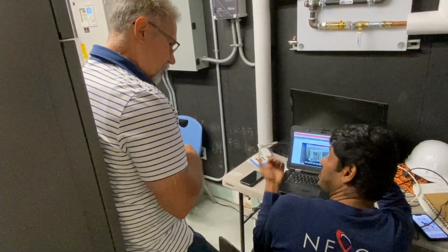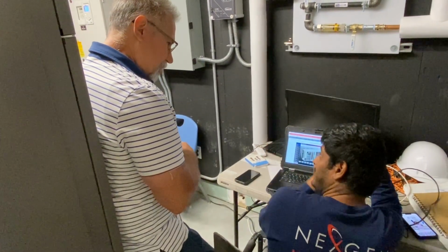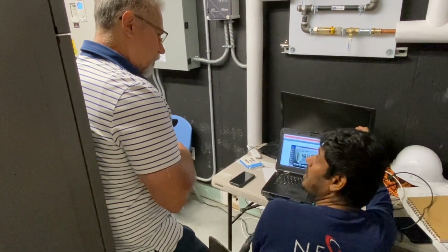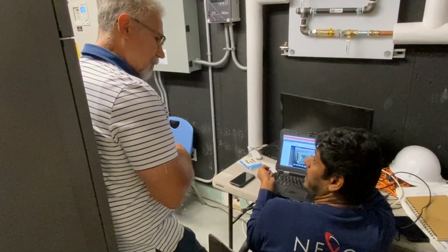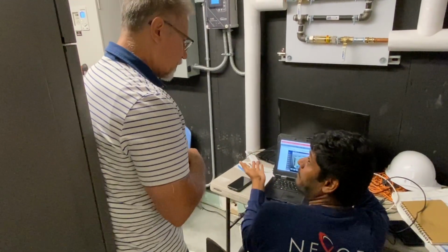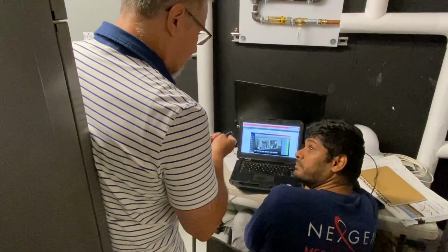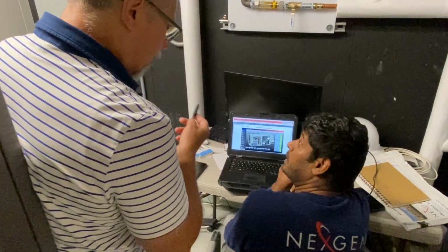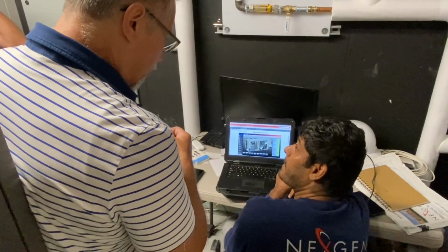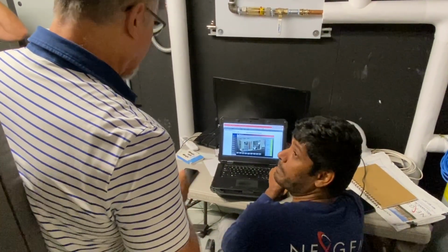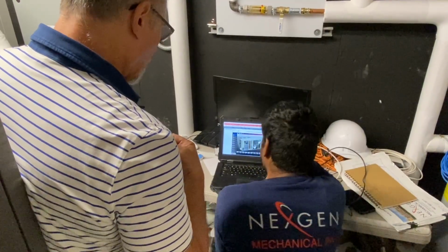We are measuring the outside air airflow, the exhaust airflow, and the supply airflow. The exhaust fan is going to track the outside air. That is the other sequence. So the ERV is 100% makeup air, or we're closing the louvers off to a minimum percentage. It is not 100% makeup, so we're not 100% fresh air all the time.